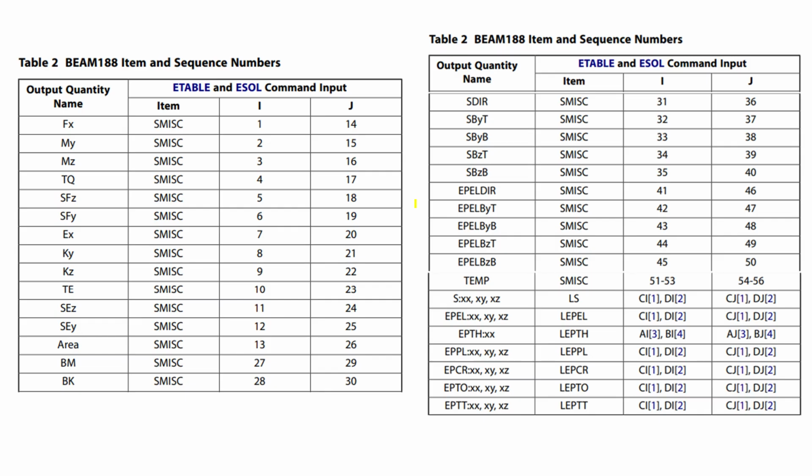And in ANSYS Fluent, in the post processing we have options for vector plot, contour, XY plot, etc. Similarly here, to get that output contour, they have given the element table I and J values. Depending upon the moment, shear force and bending moment diagram, we have to call these I, J numbers.